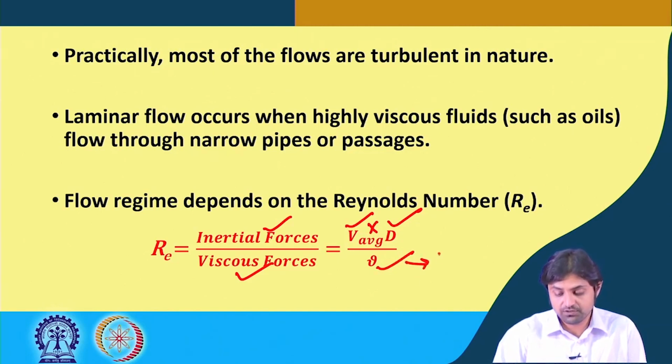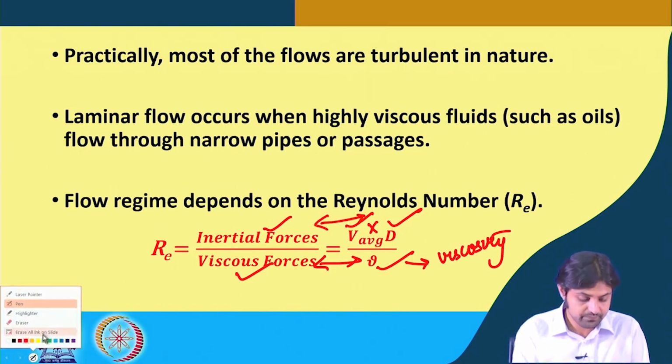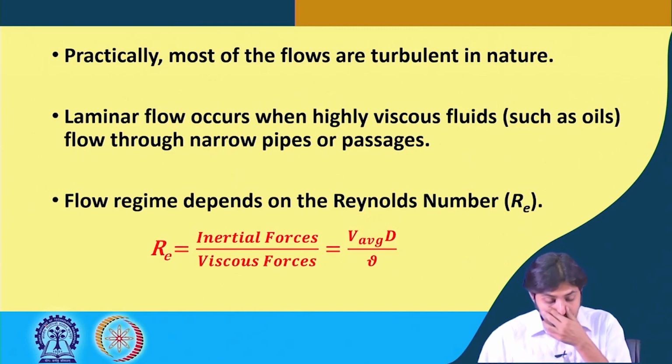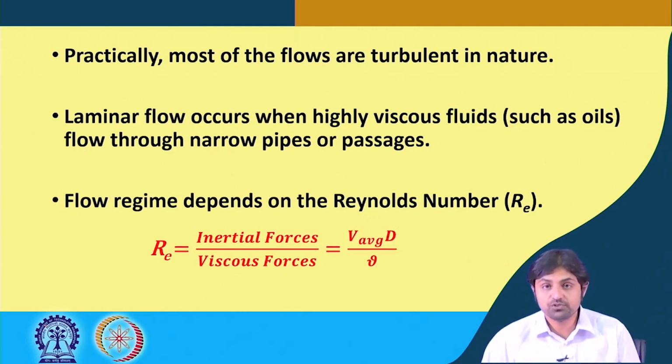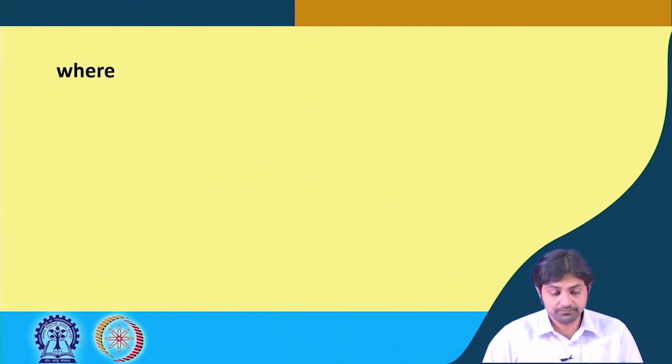So, this has something to do with viscosity, okay, that is why viscous forces, you see, and this has something to do with inertia. This equation for Reynolds number is one of the most important things in this course. You will encounter the Reynolds number more than you can imagine in this course. So, I would recommend that you remember this Reynolds number as inertial forces by viscous forces.